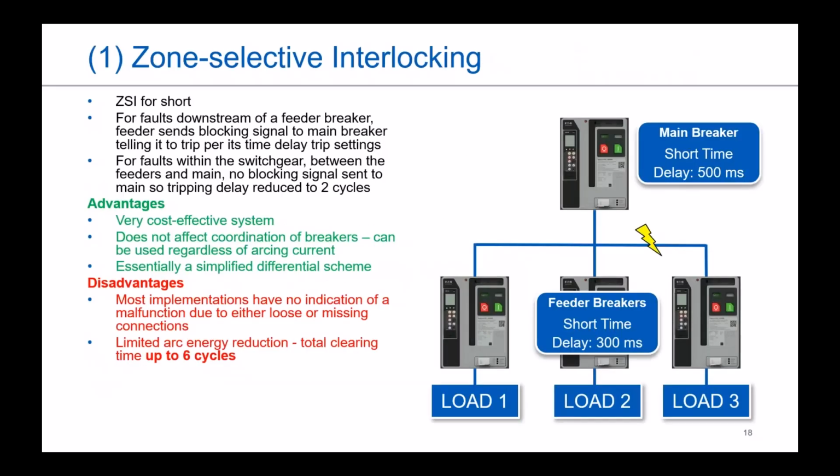So diving into ZSI. So really what this does is it's relatively cost effective. Most of the time you're just using a twisted pair connected between breakers. It doesn't affect the coordination of the breakers, because it's basically communications between them to say, hey, who's seeing the fault, who's not, and to allow you to do really a super basic version of a differential scheme to determine where that fault's actually occurring within the system and speed up the reaction time of the breaker that is capable of clearing the fault in a given area.